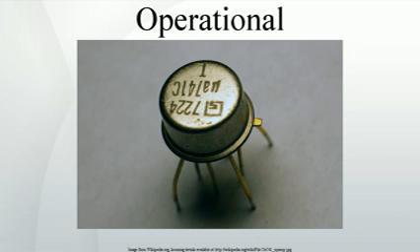Output amplifier. Output transistors Q14 and Q20 are each configured as an emitter-follower, so no voltage gain occurs here. Instead, this stage provides current gain, equal to the hFE of Q14, resp. Q20. The output impedance is not zero, as it would be in an ideal op-amp, but with negative feedback it approaches zero at low frequencies.